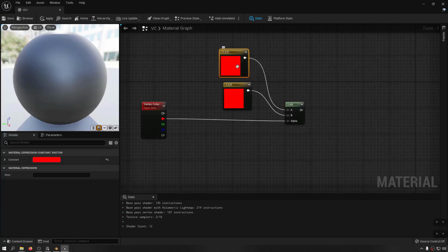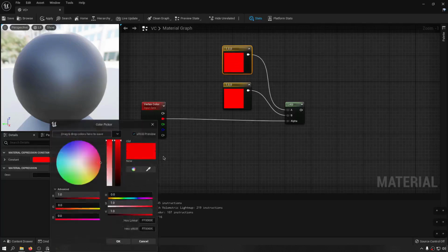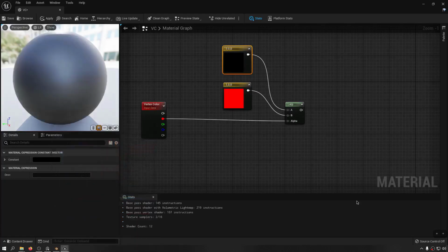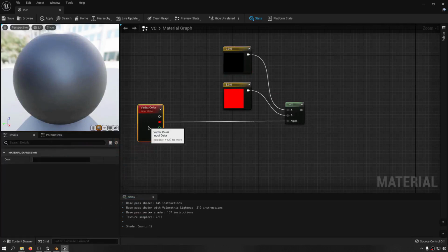And I've purposefully put this into A so that there's something, but you can safely set it to black. So we're going to use the red vertex color as a mask, and A means 0 and B means 1. A means no, B means yes. So logically we are going to tell it, hey, use the vertex color where it's red, put the B, show the B for us.